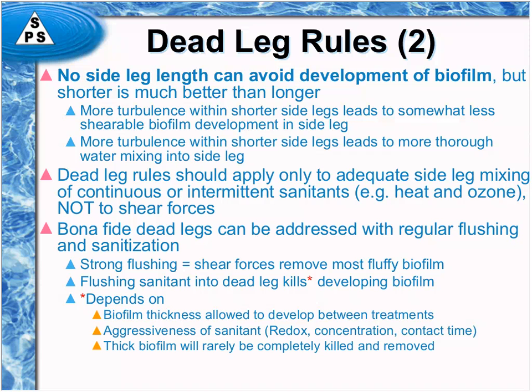And just be aware that a thick biofilm will rarely be completely killed or removed by any kind of chemical sanitant. Hot water can completely kill it, but it will not completely remove it. And if it's not removed and left in place but dead, it will become food for biofilm regrowth later.